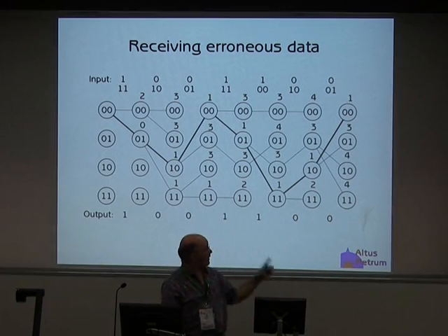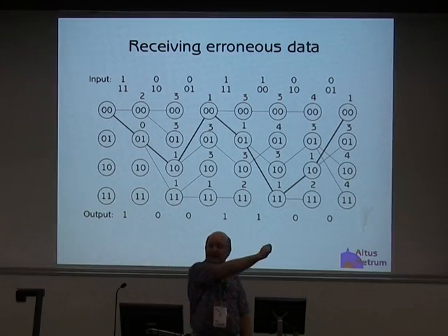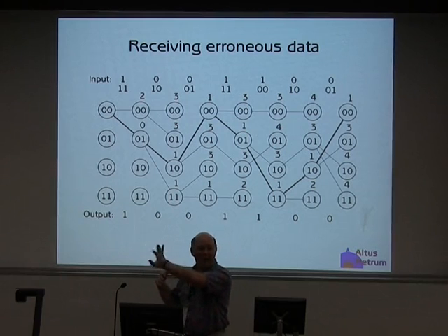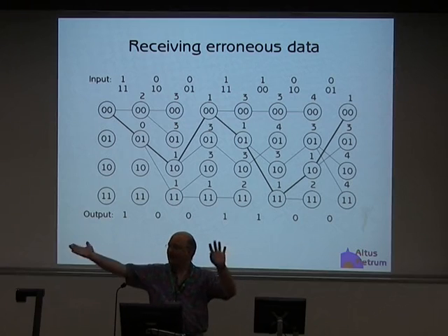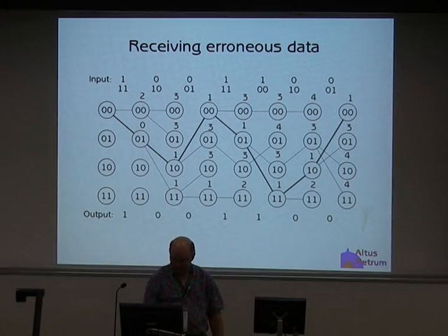And so that's really how a Viterbi decoder works. It decodes the entire packet, and it starts at the end and walks its way back to the beginning to pick out all the correct bits. There are optimizations involved where you can say, I don't have to go all the way back to the beginning. I can start partially decoding the data after I've gotten a bunch of bits in, and it's unlikely that older bits will have changed.